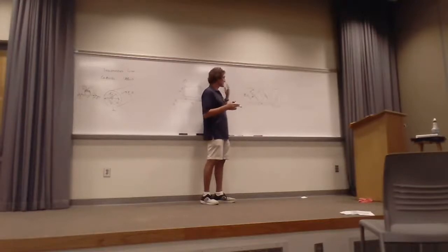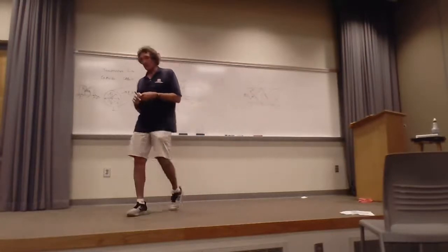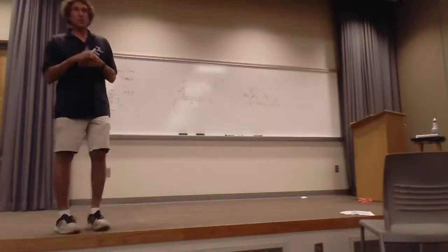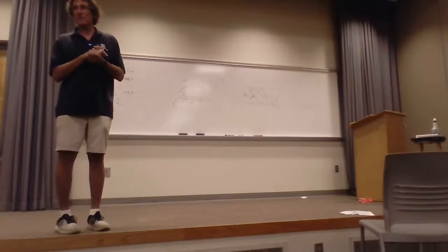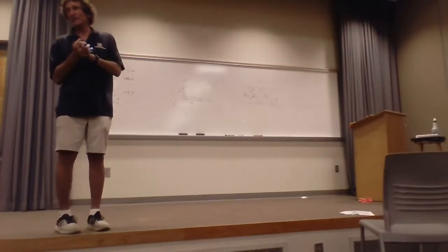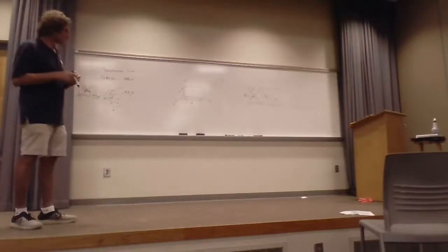Now, the thing about it is, if you can do this, it's called the summation of two plane waves that have the same tilt angle, same polarization. You can do that so that the boundary conditions at these edges are 0, and that does solve the problem. I'm going to do it in terms of a solution of Maxwell's equations. This is the exact way, it's the way engineers do business. They don't talk in generalities and say, oh well, that's it. We actually solve the equation.